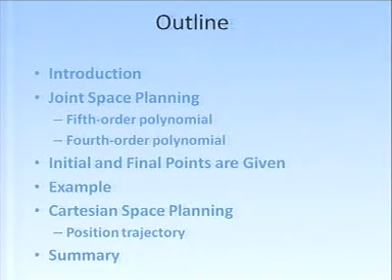So, today we will be starting with a new topic. This is chapter 11 of my book. First, we will talk about the introduction, where we will see why trajectory planning is important. Then we will see planning in joint space, that means you define the joint motions, not the end effector motion. There you will see that a fifth order polynomial is one of the useful functions to define the joint angles.